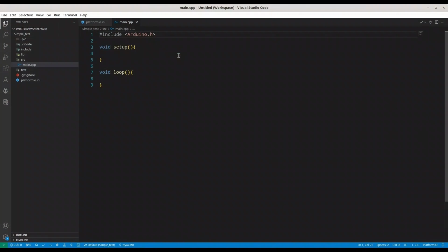So guys, before start coding, I have to explain you one additional thing. You have to check documentation for your microcontroller's board, and particularly pinout. Because with external wake up method, we can use only RTC pins. And with touch wake up methods, we could use only pins that are considered to be touch pins. You cannot use just any general input-output pin for it. So for this episode example, I am going to use my pins 32 and 33 from my ESP32 microcontroller. These 2 pins are both touch pins and RTC pins. So I can use both methods.